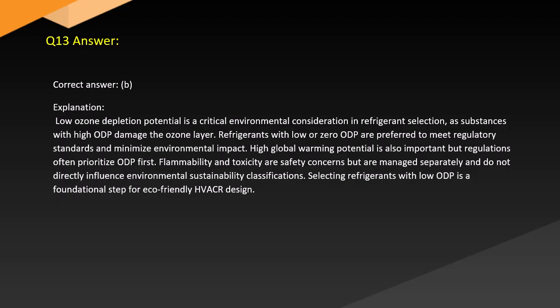High global warming potential is also important, but regulations often prioritize ODP first. Flammability and toxicity are safety concerns but are managed separately and do not directly influence environmental sustainability classifications. Selecting refrigerants with low ODP is a foundational step for eco-friendly HVACR design.